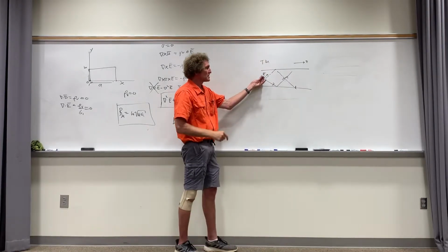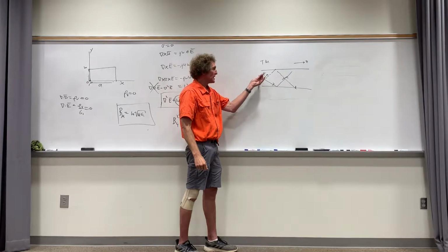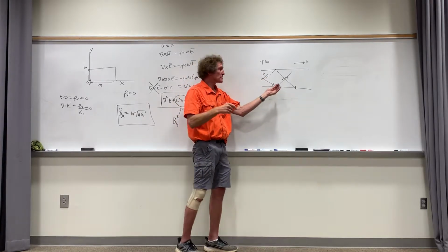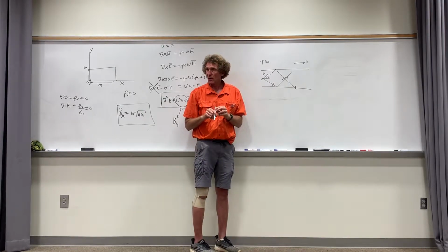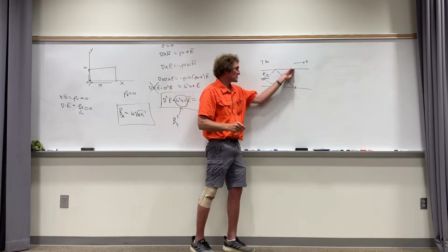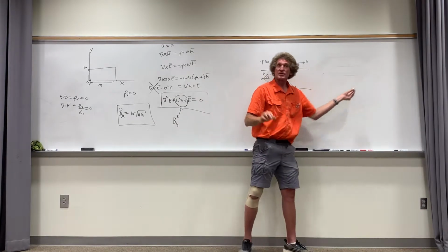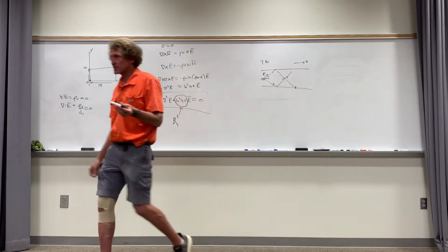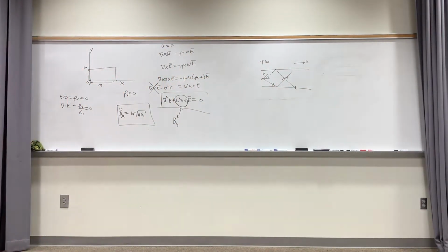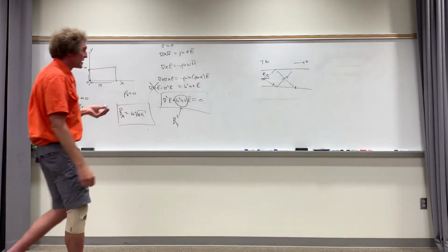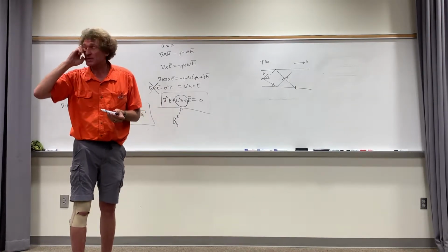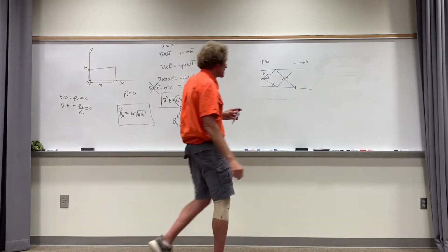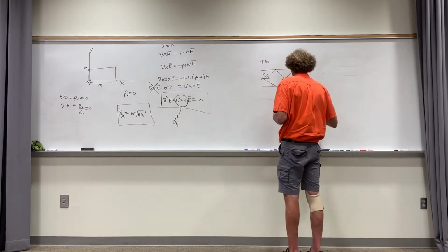The magnetic field is out, all right? The E field smashes there. The E field's got a component in the direction of propagation. Do you all see that? Why? Because of the way it's ricocheting. It's bouncing this way, this way, this way. So there's no magnetic field in the direction of propagation, but there is an electric field. Can you appreciate this? This would be for the TM mode. And thank God for the TM mode. It means there's no electric field in the direction of propagation. So what we can do, we can use that to our benefit.